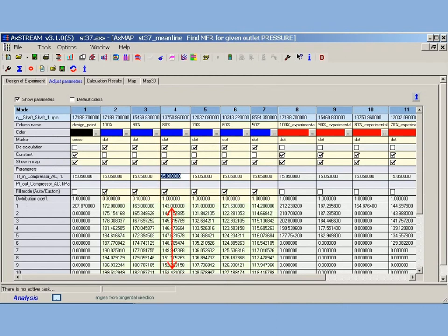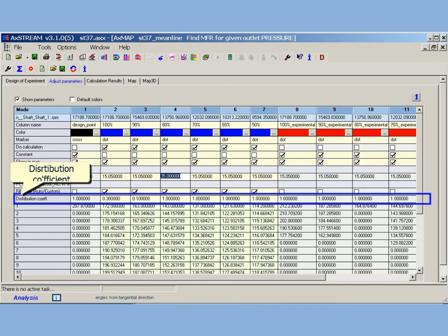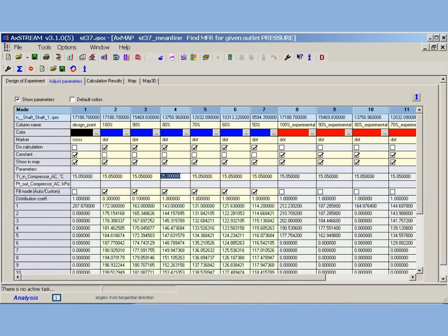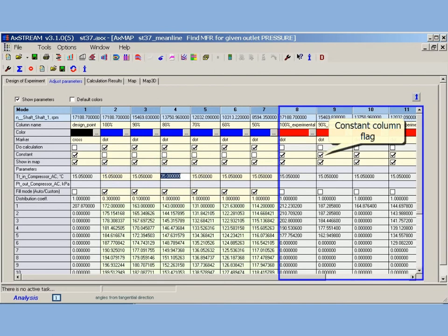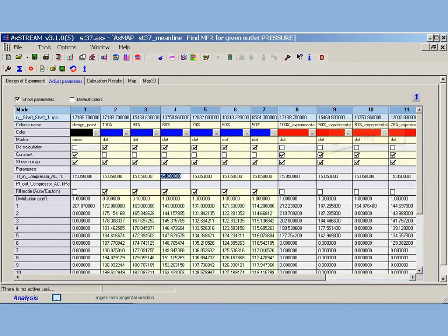By default, row values are evenly distributed between minimal and maximal values. An additional parameter controls the distribution gradient. If required, the values of row parameters may be set manually. Some series columns may be declared as constant. They are not calculated, but are open to input data manually or with copy-paste. Constant columns are used to present external test data.